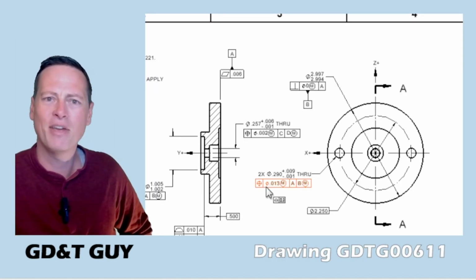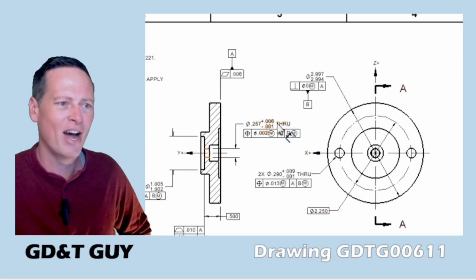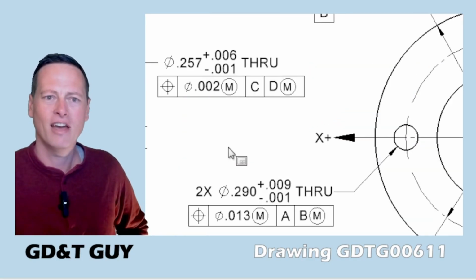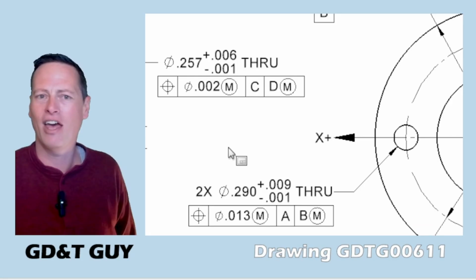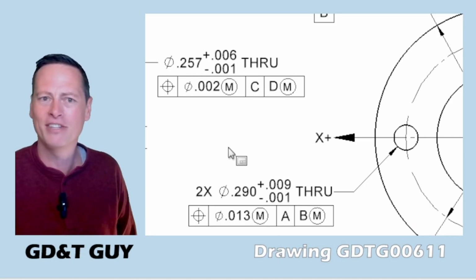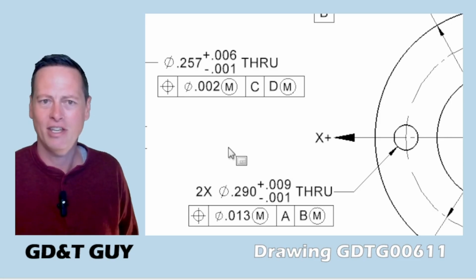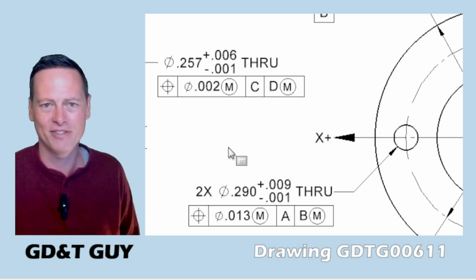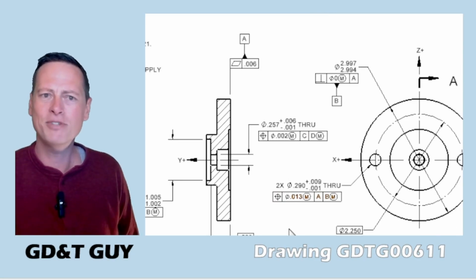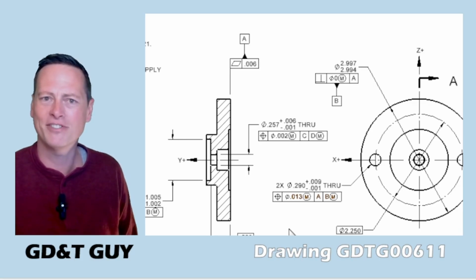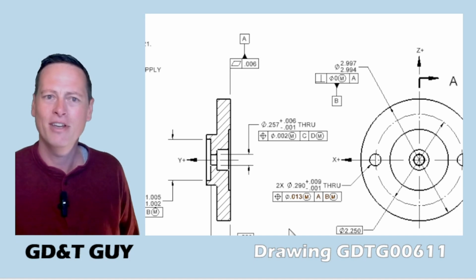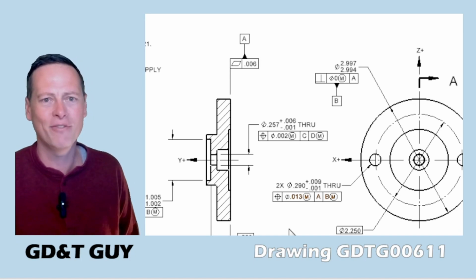What you will see is that they want us to put in these little X, Y, and Z arrows. I guess this defines the origin and the mutually perpendicular planes of the datum reference frame and assigns them an orientation, even without the tertiary datum reference. Seems like kind of a way to accomplish that 6DOF constraint and to identify a coordinate system without having to introduce a non-functional tertiary datum feature.